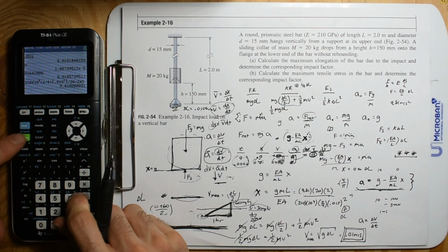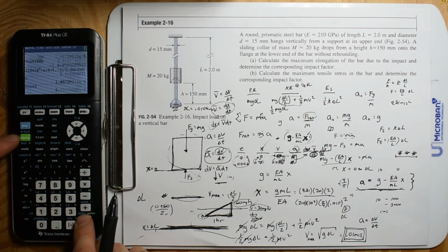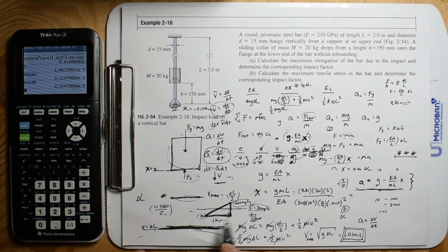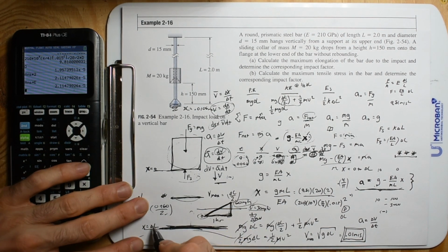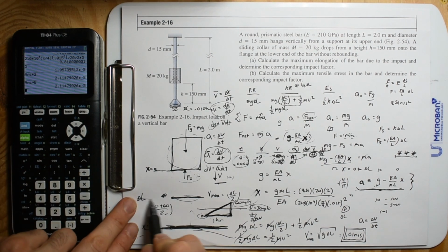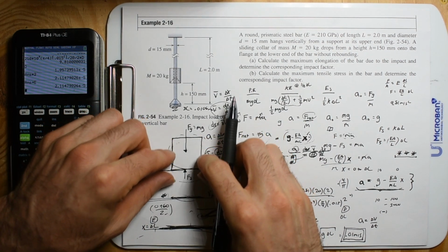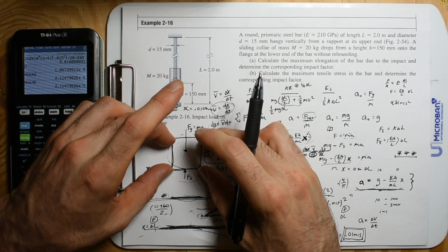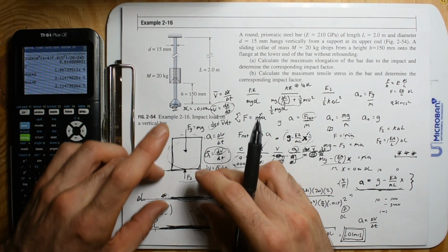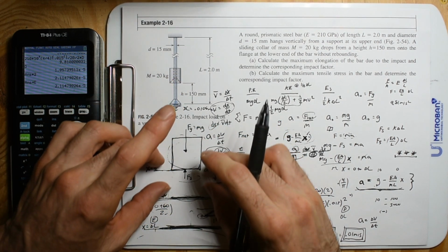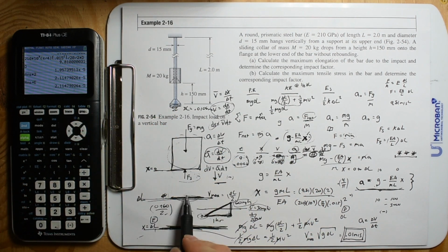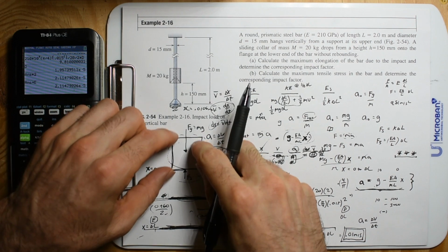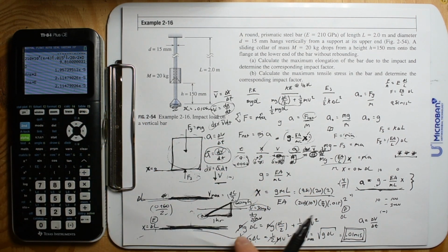So my alpha d, I need to multiply this by 2 and store it as alpha E. So my change in length for this problem is alpha E. This is the static. If I just statically loaded it, we'd get down to there. If I dynamically loaded it, dropping from 0 height, I go past this point, and then it oscillates back and forth, and then if there is damping, it settles right at that, and they call that the statically loaded change in length.